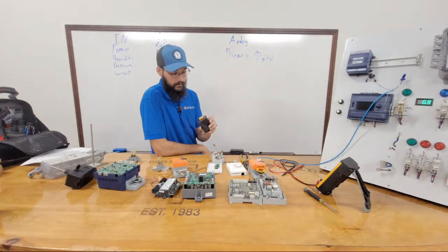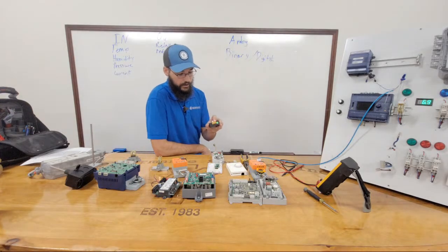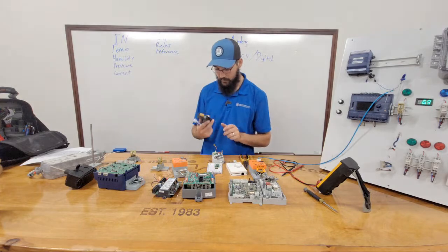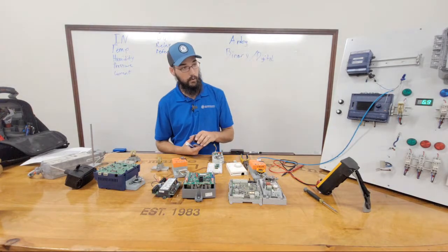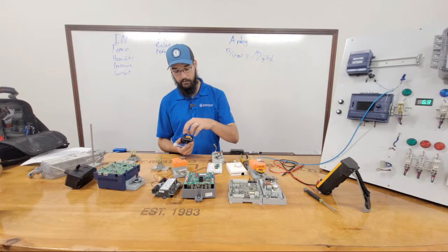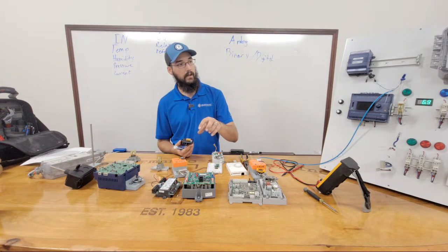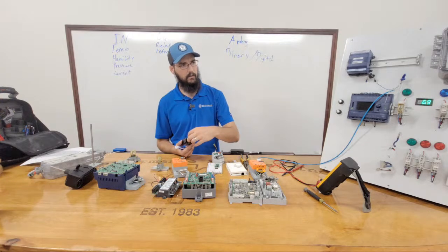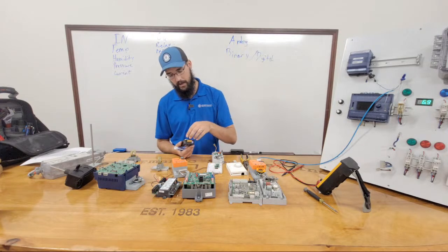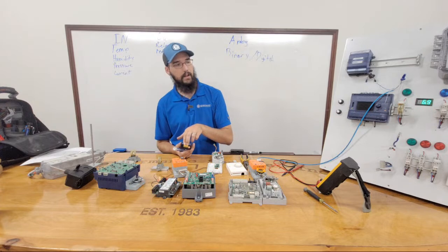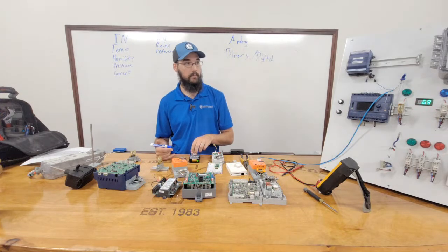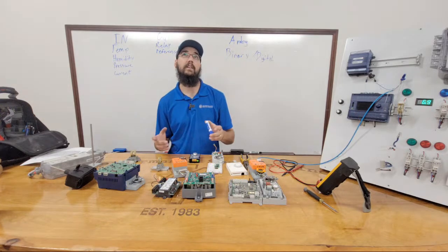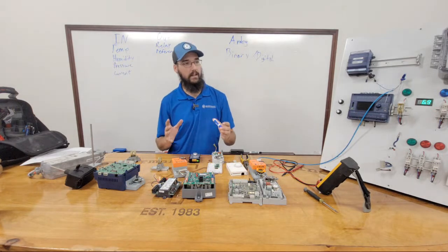So if I would have remembered to get the resistor, I could show you that. I'd be able to put my signal generator in a milliamp mode, and then I could put the resistor in parallel. And then I could take a reading, because normally on a milliamp signal, you'll read some kind of weird standing voltage, right?